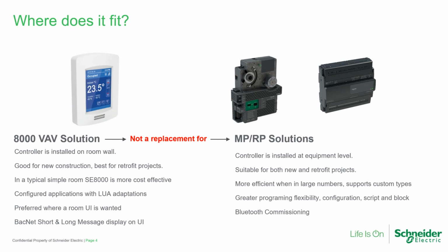This particular device is self-contained in a wall-mounted controller that's hardwired up to the VAV box, where the damper actuator and the pressure transducer and all of that lives. And at the end of the day, all of that comes back to a nice, clean interface on the wall that can address the VAV box and do the air balancing without any software, without any licensing, nothing.